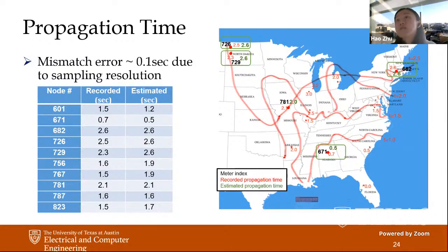And that's what triggered the 2003 blackout, and also part of the reason for the 2009 or 2011 San Diego blackout as well. So usually to trigger this large-scale cascading failure, it is because we are lacking transmission capacity due to transmission lines being out of service. So this frequency behavior would be coupled with lines out of service, and they can trigger a large blackout.